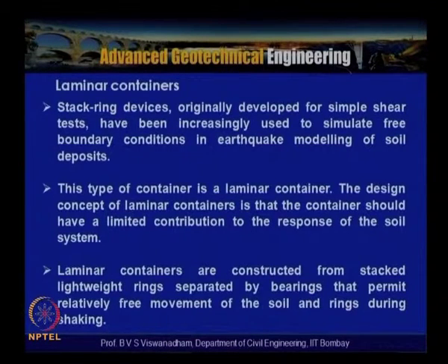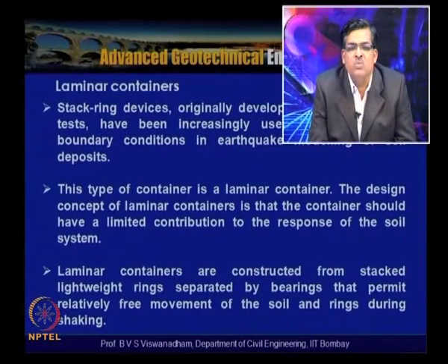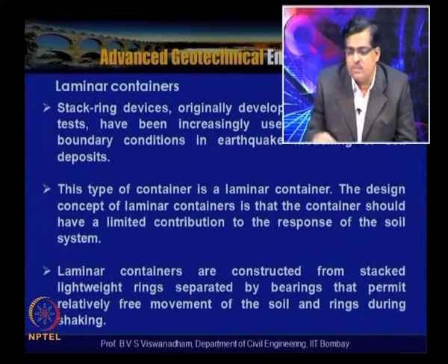The design concept of laminar containers is that the container should have a limited contribution to the response of the soil system, and it should not cause the reflection of waves. Laminar containers are constructed by stacking lightweight rings separated by bearings that permit relatively free movement of the soil and the rings during the shaking. These laminar containers are found to simulate the actual behavior in the field, so that they induce identical deformations at the edges as well as in the center.